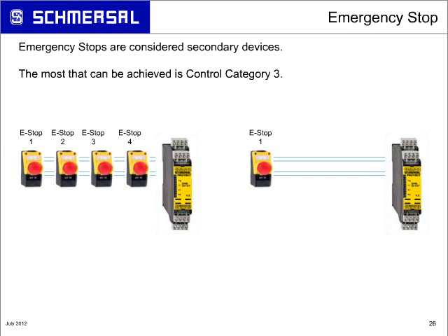It could be a catastrophic failure. Your core safety system, such as your door interlocks, no matter what the design, maybe a failure has occurred and the machine didn't stop, the E-stop is there as a backup, as a secondary means of shutdown.